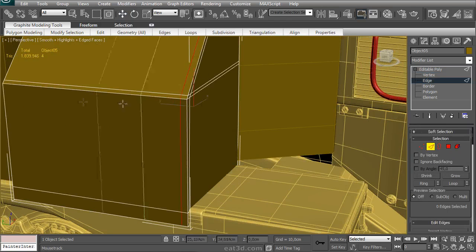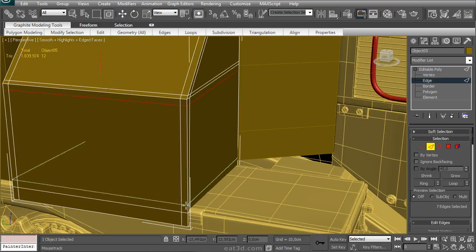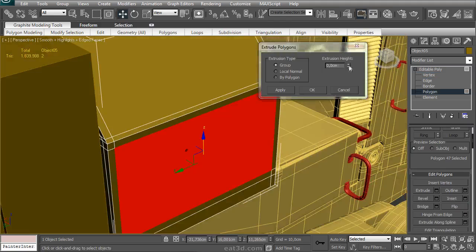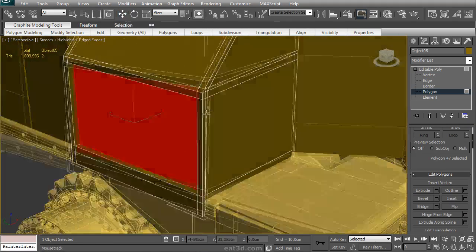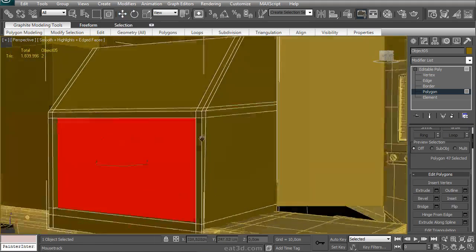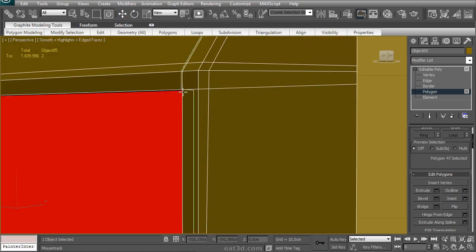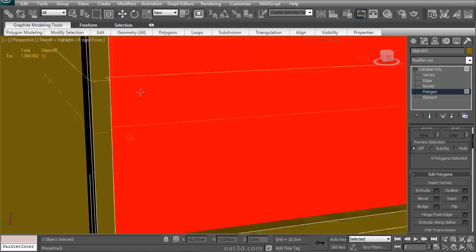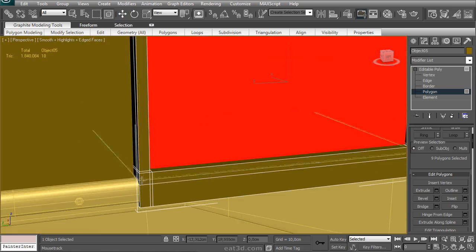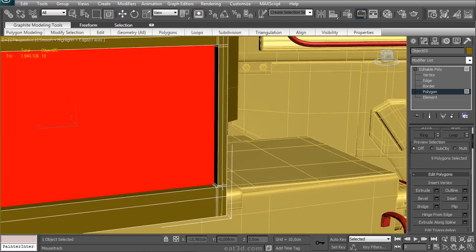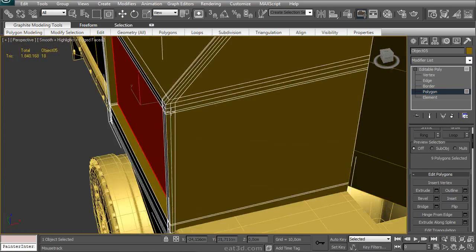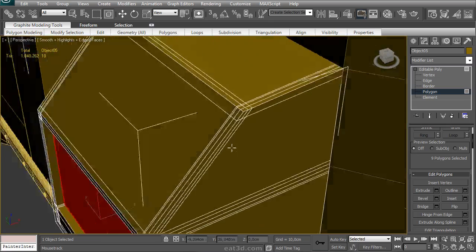Right, so this part, I'm just going to remove it because I realized you take that sort of inset shape for a rounded object, and this actually is a square part, so it's better to use these loops that go all around the object. Just better to work with. There we are. And adding a few of those there to make sure those edges are smooth and right. Okay, that looks pretty good.